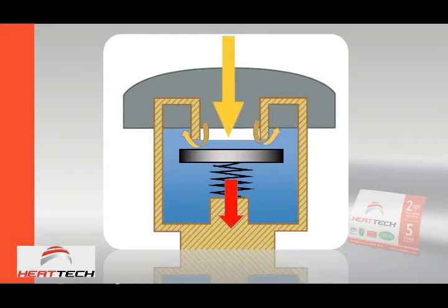So what happens? The pressure turns around. So this pressure, like the thermosiphoning that we showed, creates a negative pressure, it needs to move down. It overcomes the spring, plus you have the air pressure coming from the top that pushes down onto this disc. And as soon as the air pressure is higher than the suction of the water, it will allow air. You see how the air comes into the system. And the more it sucks, the more air will come into the system, and that allows the pipe to fill with air from the top downwards.